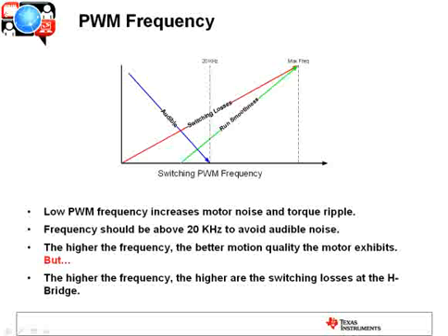Also, the faster you switch the frequency, the smaller the ripple current, which directly relates to how smooth that motor runs, how quiet that motor runs. That's going to go down. The downside is as you increase the switching frequency, the switching losses start to increase. Therefore, your efficiency does start to go down. So it's somewhat of a trade-off, and the exact switching frequencies many times will just depend upon the application.